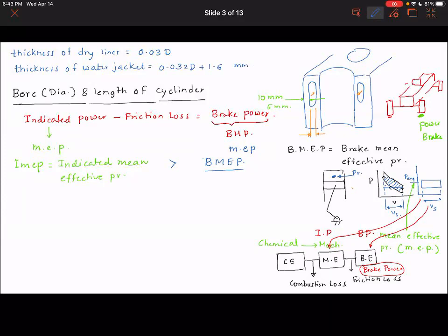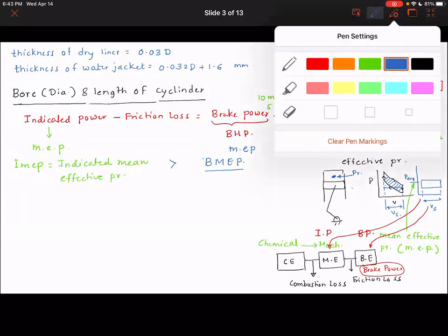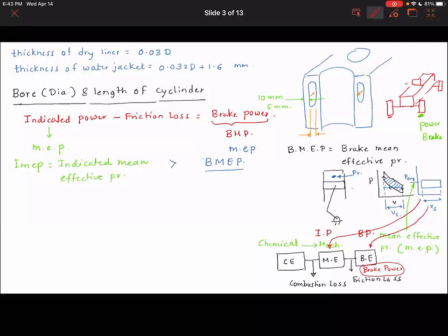Why not? And some of you may ask this question, and as a design engineer, you should. Why not look at the maximum possible pressure and then find out the cylinder dimension? To answer that question, yes, certainly, if you want your engine design to be super bulky, if you want to over design your engine, by all means, we can go ahead and use the maximum possible pressure.